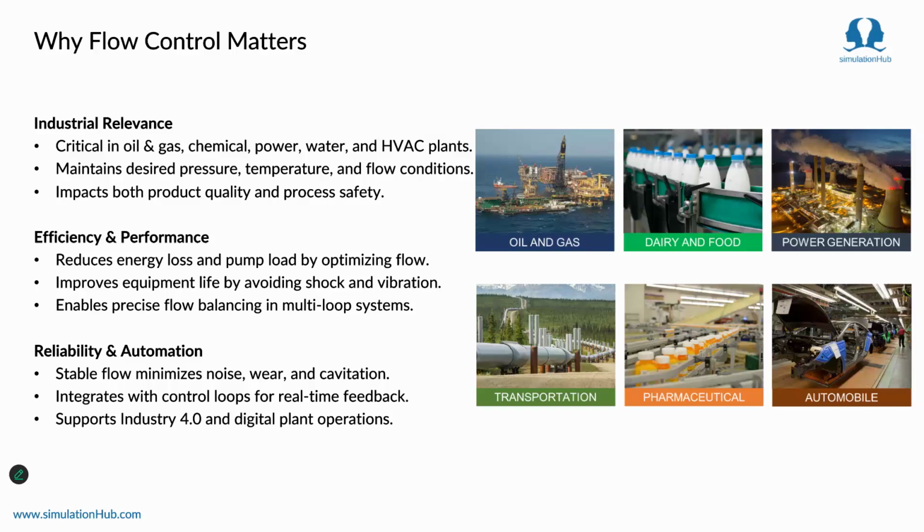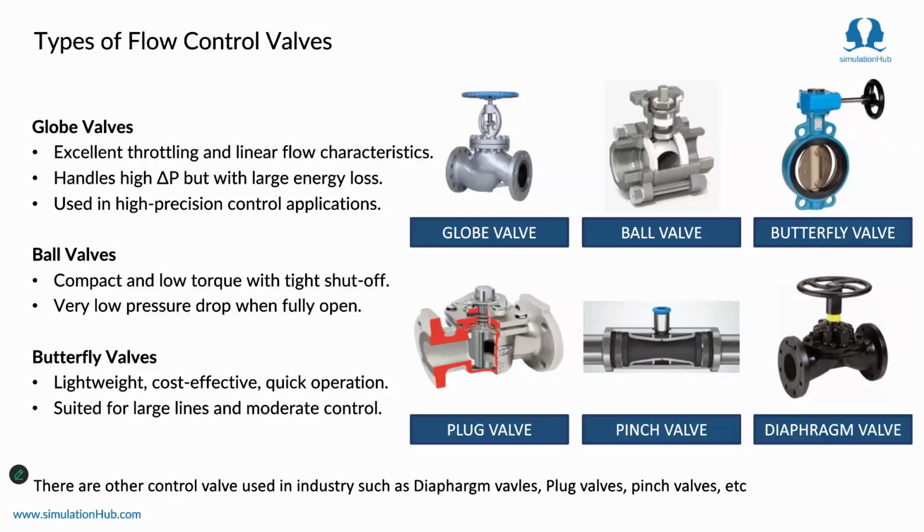So moving along, we have the industry standard control valves. Globe is the best example here. Globe is excellent in throttling the fluid. It gives you precise control as the travel is linear. It gives you a very good control over the process fluid.